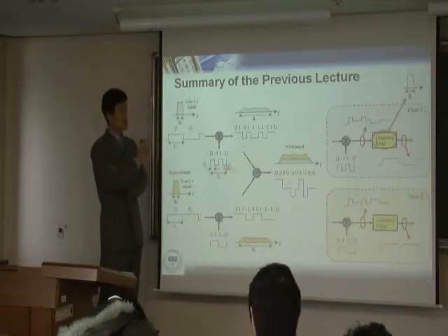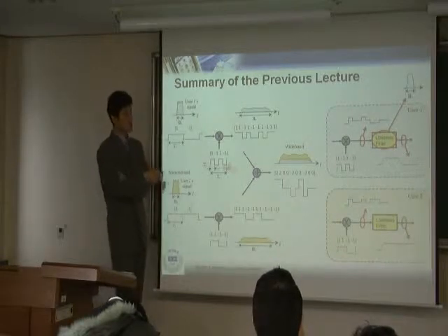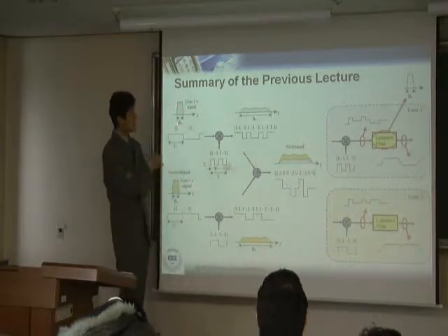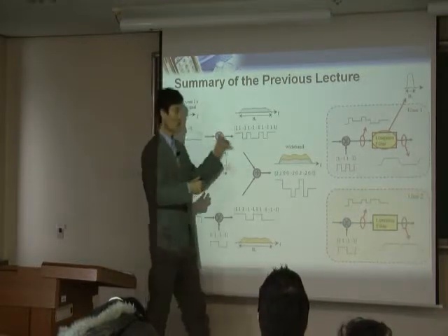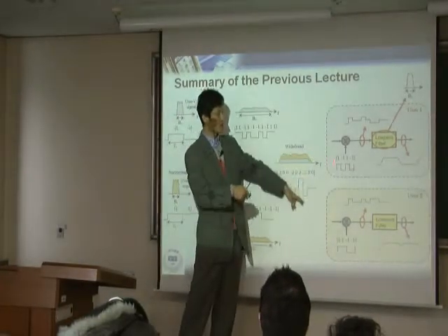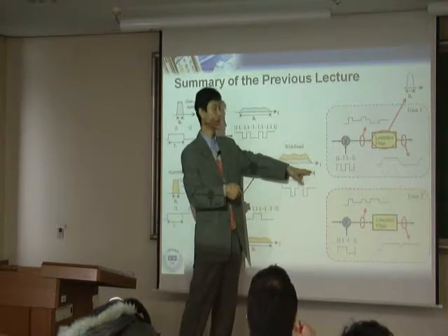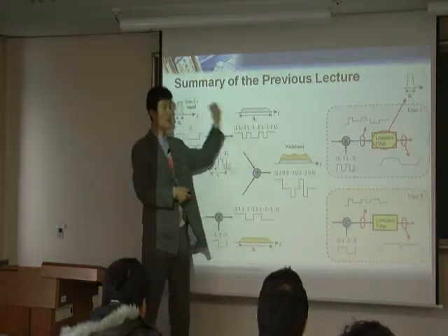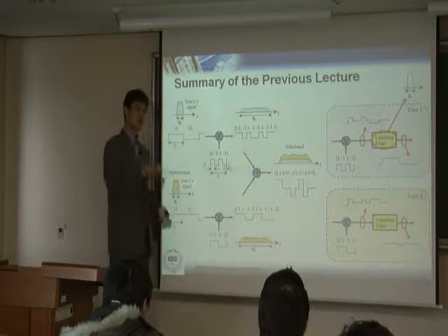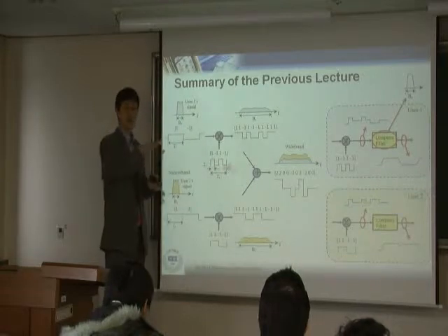That's the open loop. But that open loop power, of course, is not accurate. So once this guy decides its own transmit power based on the open loop and then transmits, this guy is not happy about that power, so this guy later gives feedback. That's closed loop. Feed it back, saying, okay, your power is a little bit higher than my expectation. Please lower a little bit. Then this guy does a fine tuning.